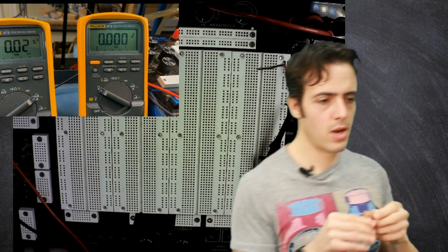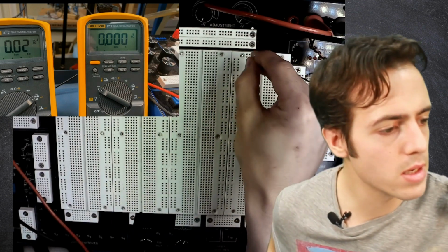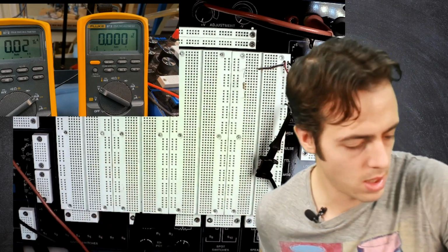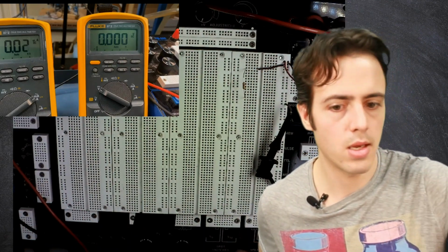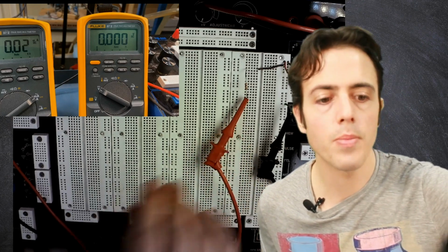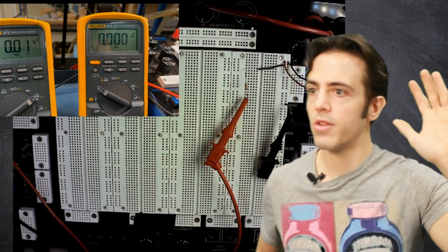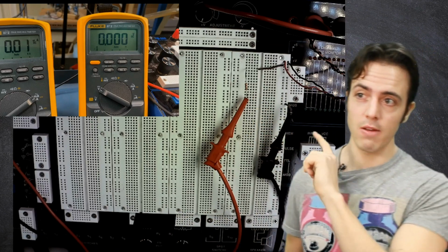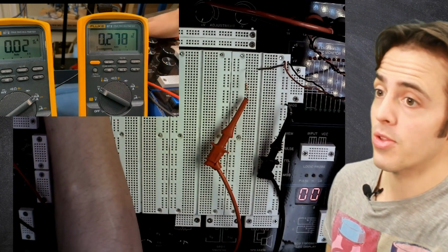Taking resistor 2 out, popping it back into the circuit, and connecting the... There we go. So we've now got resistor 2 in here. I'm going to do the same thing, take it up to high voltage. I know that the maximum voltage that this one could take is quite a bit larger than 40, so I can take this all the way up, and I'm going to get you guys to do the same thing, record those voltages that we go through.